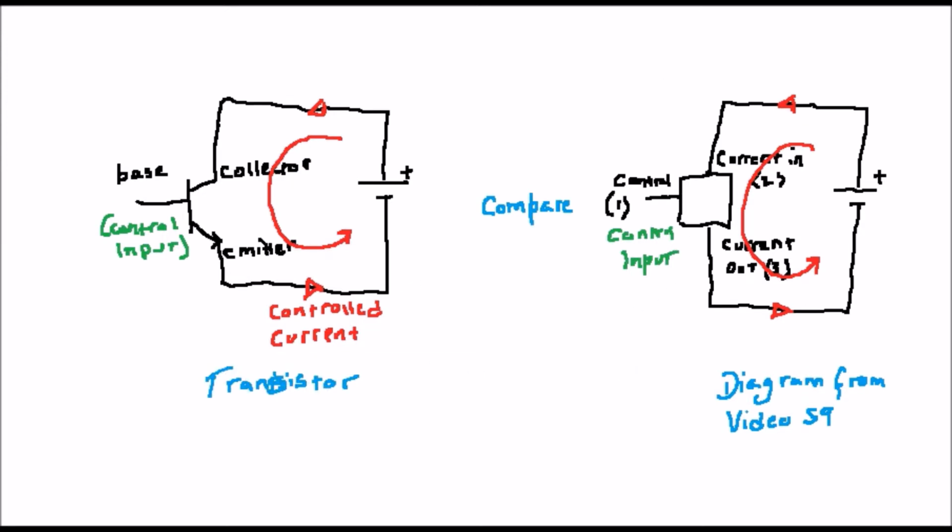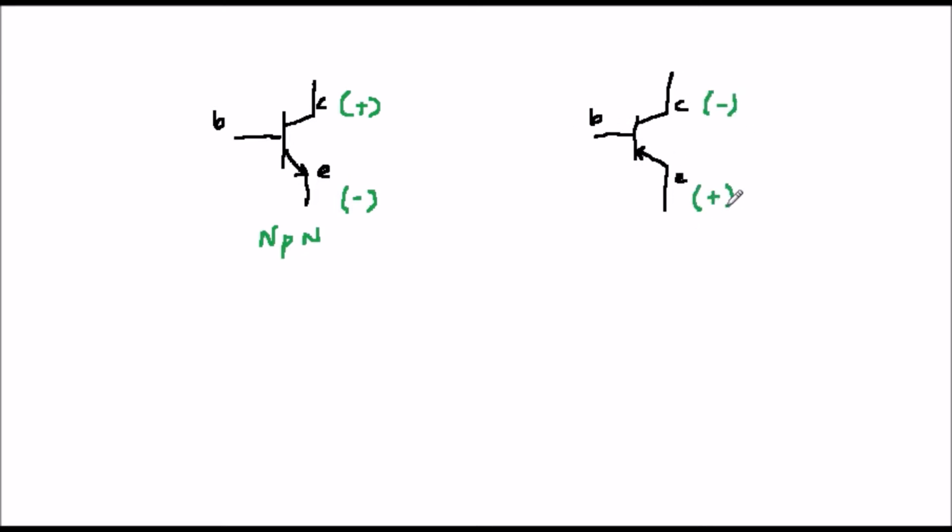Transistors come in two types, NPN and PNP. At the simple level, these differ only in the polarity of their power supplies, which are the opposite of each other. The transistor shown in the first example was an NPN type. You might note that the arrow on the emitter lead in both these types points in the direction of current flow.